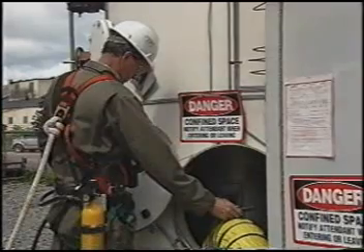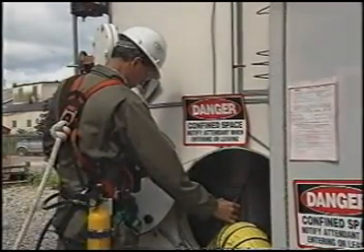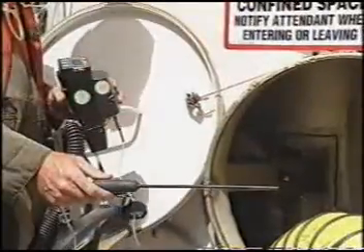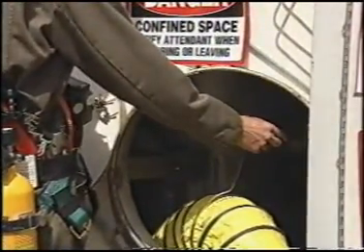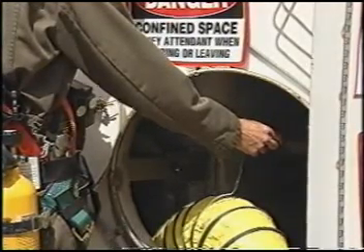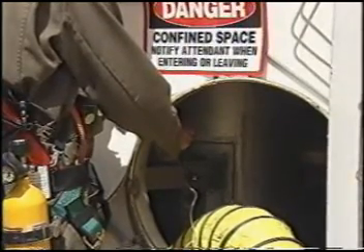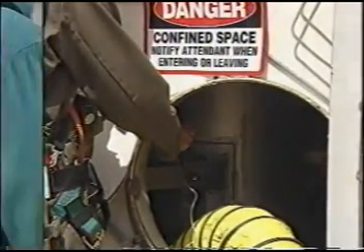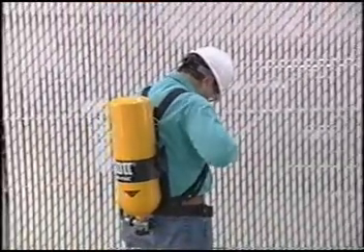Check the air above and below the entryway of a confined space and around the interior. Make sure any work outside the confined space will not affect the atmosphere inside, such as by drawing in harmful gases through ventilation. Take these steps from outside and continue to monitor the inside atmosphere until all the workers in the confined space leave. Use the right equipment for entering a confined space.